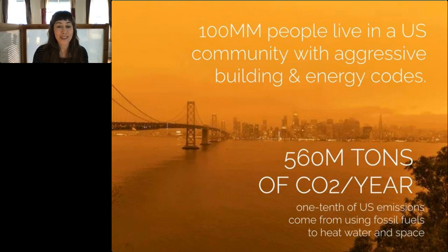You are going to start seeing troughs from solar output at times when there's not enough demand to sop up that solar electricity. So the duck curve that you're seeing in California creates little ducklings at its section of the distribution infrastructure. And then as you begin to see this retrofitting of space heat and water heat, as well as an increased adoption of building cooling on the electric side, you're going to see this real change in the real-time power profiles and load profiles of buildings.